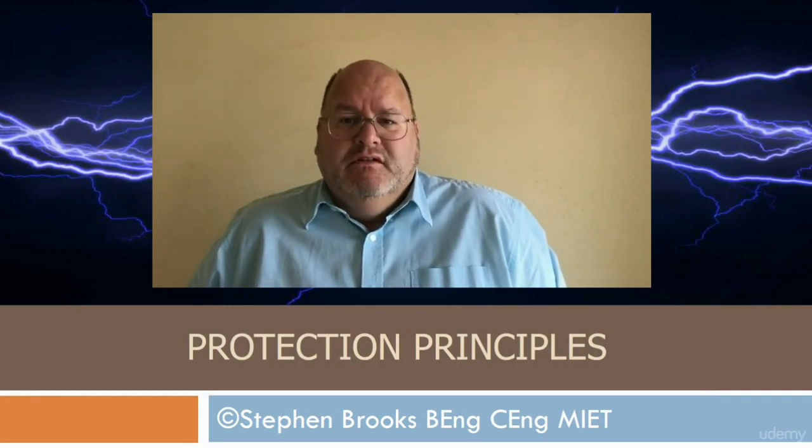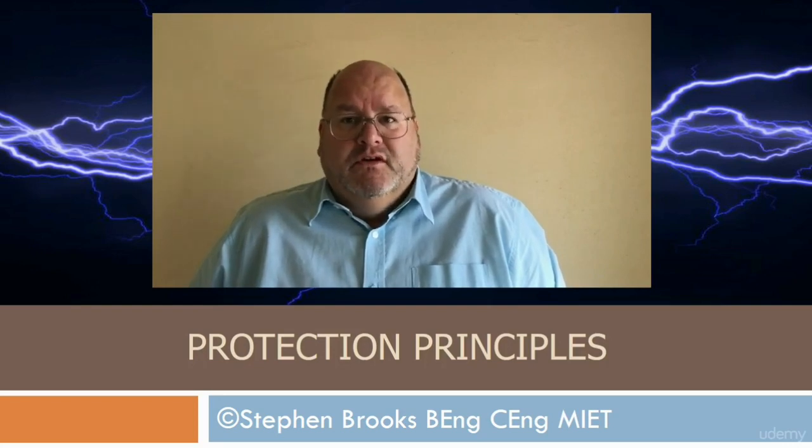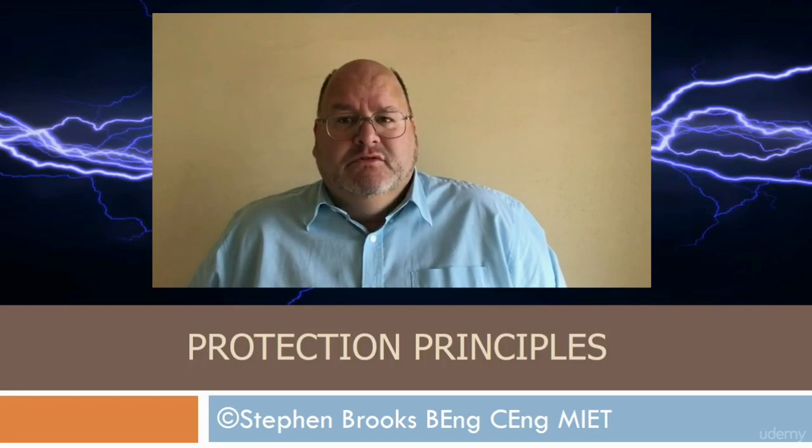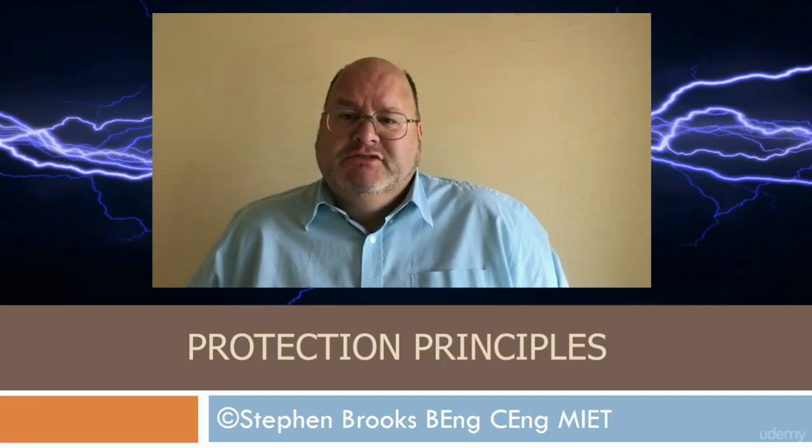After the first module, in which we looked at the equipment that we use for the protection system, in this module, we look at the basic principles behind protection systems. By the end of this module, you will understand some of the principles behind protection systems, including the importance of clearing a fault quickly whilst keeping as much of the healthy system connected as possible.